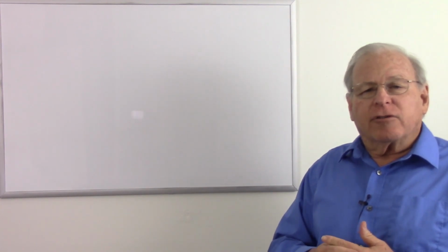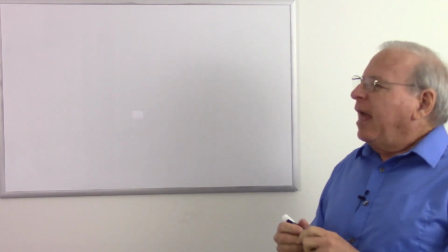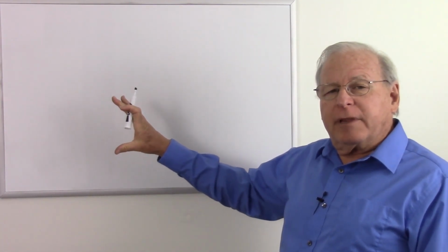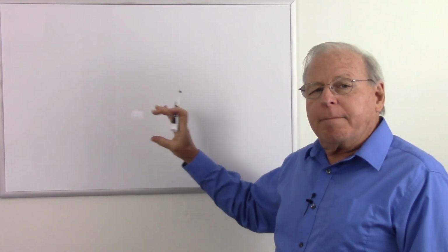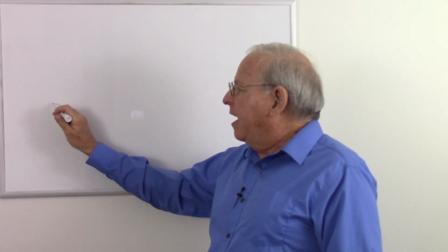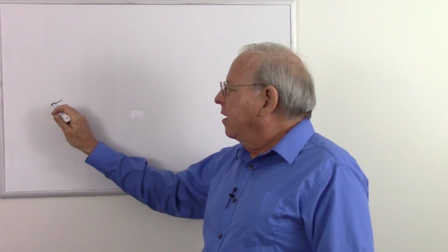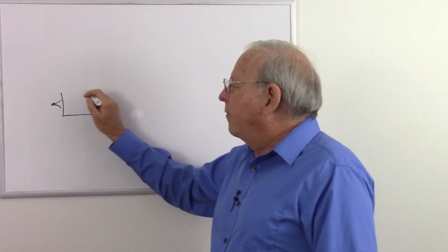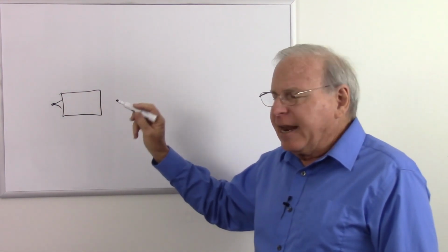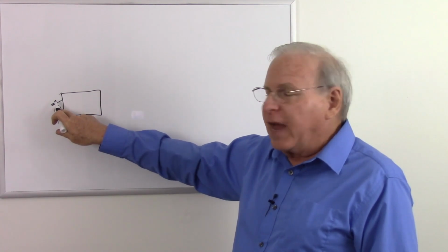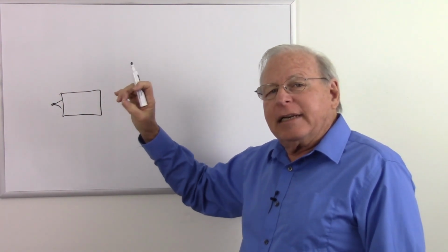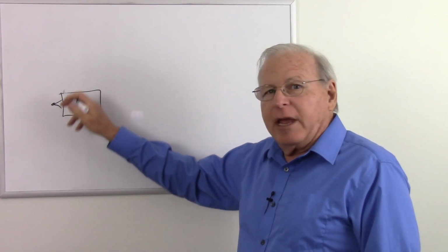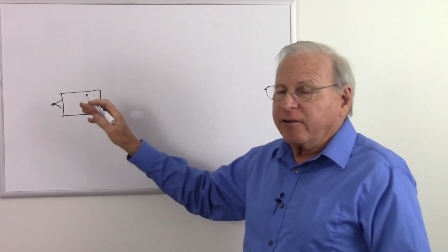Now, more modernly, we also have electric analog computers. And let's take a look at how one of those might work. Let's say we have a system that needs an electric input based on temperature. So somewhere we have a temperature sensor. Let's say it's perhaps a thermistor, could be a thermocouple or whatever, and that goes into a system that will perhaps linearize it. What I mean by that is that the voltage that comes off of our sensor may not double as the temperature doubles. So if the temperature doubles, the voltage may go up by a factor of 4 or may go up by a factor of something less.